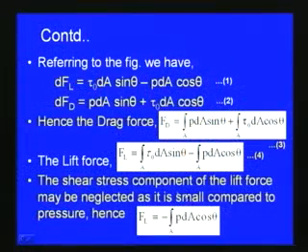So if we neglect the shear stress component as far as lift force is concerned, then we get the lift force FL equal to minus integral over A of P dA cos theta, since we consider this equation here. This gives the lift force.